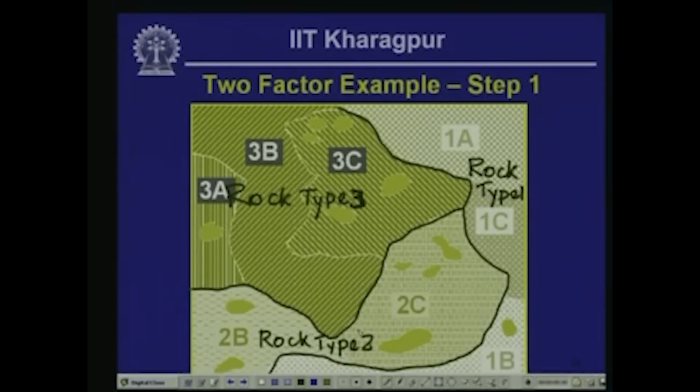Then on this map we have to superpose the areas where we observe historical landslide activity, and these areas could be in the form of areas where landslide scarps are visible and areas which are underlain by landslide deposits, such as deposits that get generated because of landslides, such as debris flow and slope failure deposits basically, and those are indicated by these solid shaded areas.